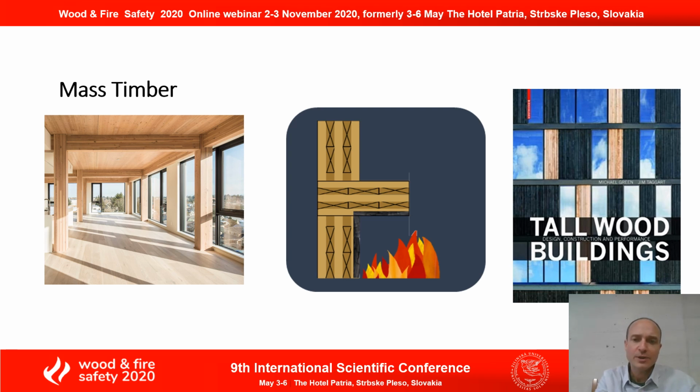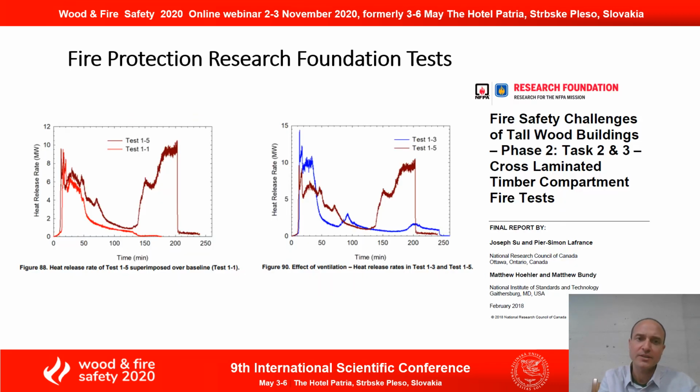And so one question as we're coming into code adoption in the United States is, how does mass timber perform under fire? So you can see in this Carbon 12 building, there's a lot of exposed CLT, exposed glue lam, and we understand how wood chars, that's very clear. But CLT and glue lam in these things have adhesive layers between each of these solid wood pieces. And so the adhesive performance determines a lot of the fire performance of the engineered wood product.